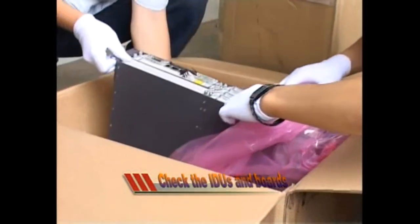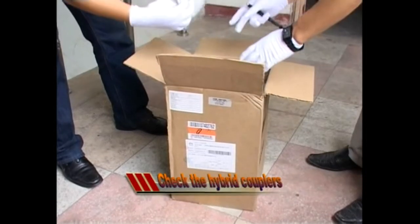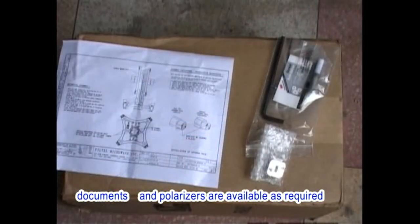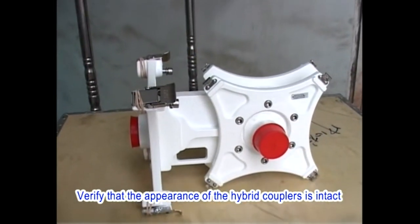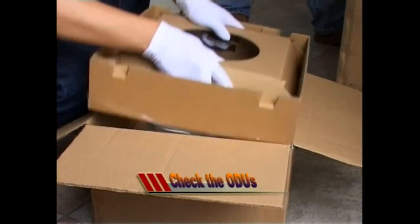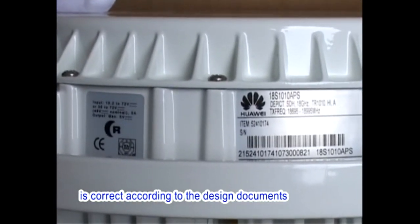Check the IDUs and boards. Check the appearance of the IDUs. Verify that the boards and installation accessories are complete. Check the hybrid couplers. According to the packing list, verify that the hybrid coupler accessories such as tools, documents, and polarizers are available as required. Verify that the appearance of the hybrid couplers is intact, and also verify that the frequency information of the hybrid couplers is correct according to the design documents. Check the ODUs. Check the appearance of the ODUs. Verify that the frequency information of the ODUs is correct according to the design documents.